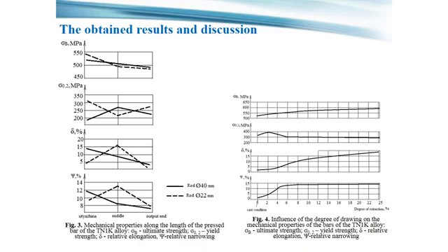Pressing was performed at different speeds: about 60 millimeters per second, 30 millimeters per second, and a third speed of more than 30 millimeters per second. Then rods with a diameter of 110 millimeters were pressed to diameters of 30 and 22 millimeters at temperatures of 1100, 1150,